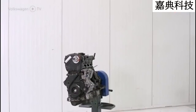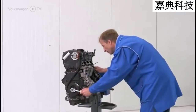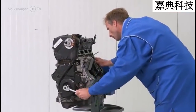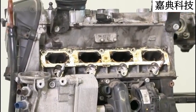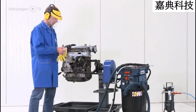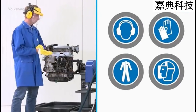For clarity, we will perform the following working steps on a dismounted engine. Before you start, rotate the engine until the valves of the inlet duct to be cleaned are closed. Close all other openings with a suitable adhesive tape. Attention! While working with the granulate blasting unit, it's vital to wear protective equipment.